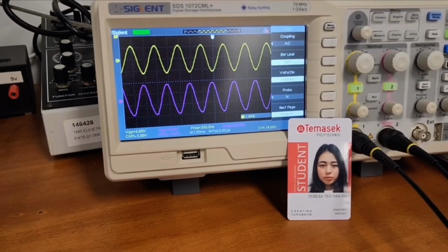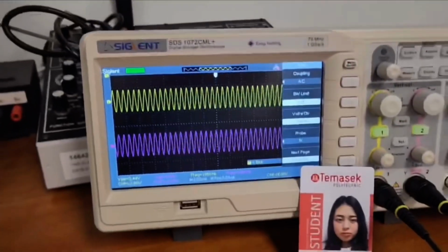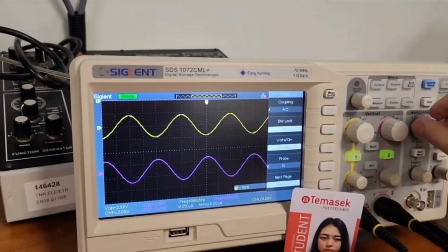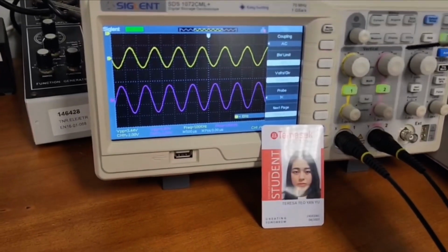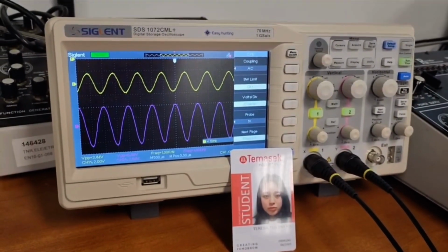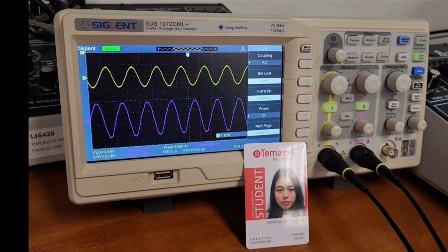So this implies that 6.32 volts is the maximum amplification. At 1000 Hz, it has a 180 inversion as well. The gain of the result at different frequency differs, so the output here once again is lesser as compared to 200 Hz. By turning the trimmer, we can see how the feedback resistance affects the output waveform. It will be amplified and at some point it will get saturated and cut off, and that is the maximum.